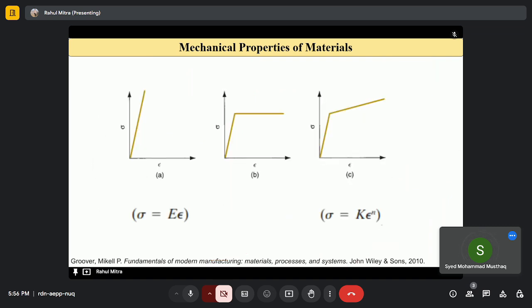Now, if my stress equals Young's modulus times the strain, with a constant slope, then the constant slope is represented by Young's modulus, or the elastic modulus, times the strain. If I am talking about engineering stress, that should equal the elastic modulus times the engineering strain.